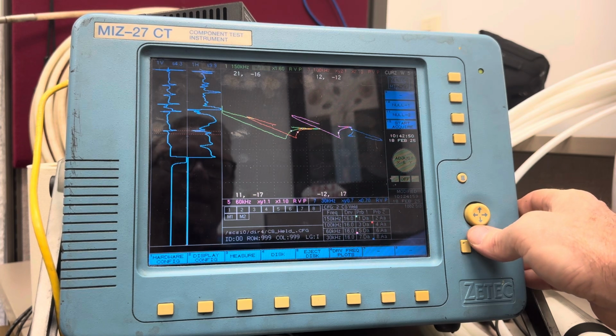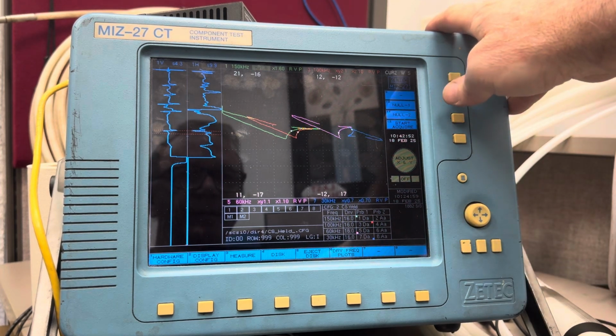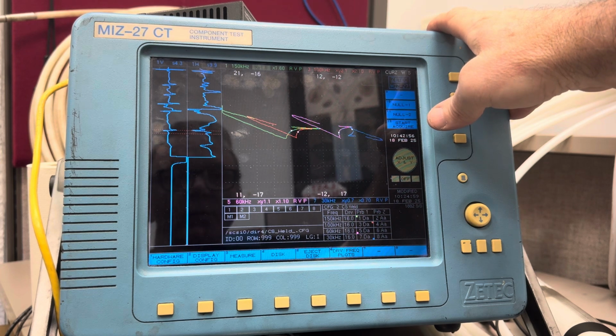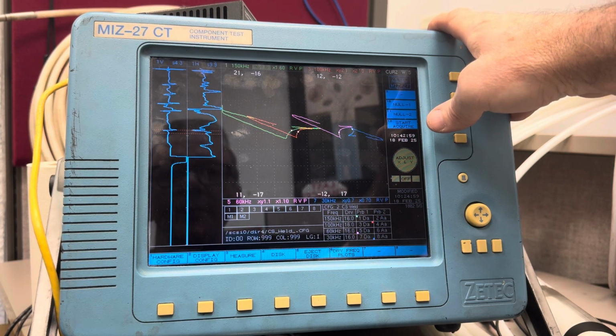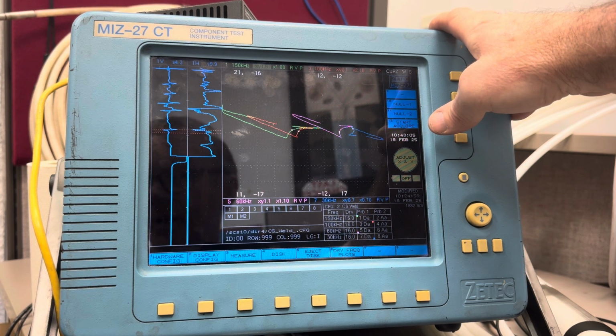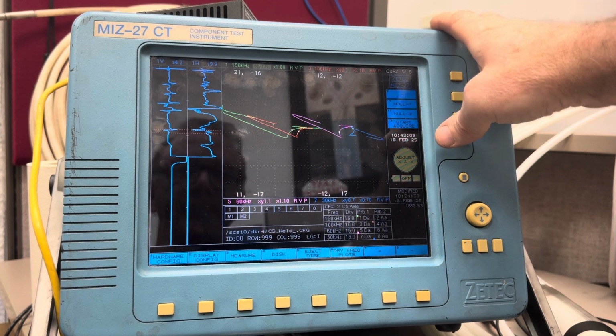So the phase angle of this particular signal, the signal from the 100% through wall hole, just a single drill hole. For this size tubing and for the probe that I'm using, this is not a great signal for a 100%er.